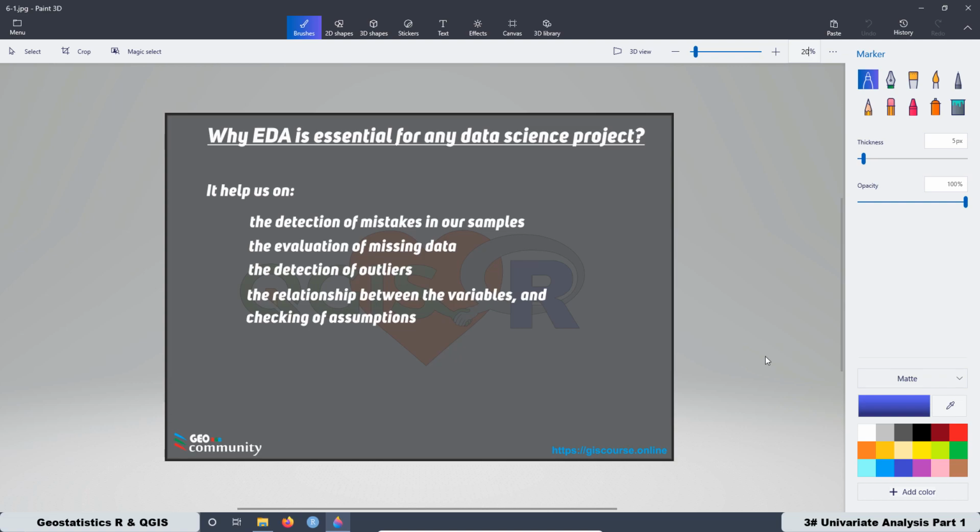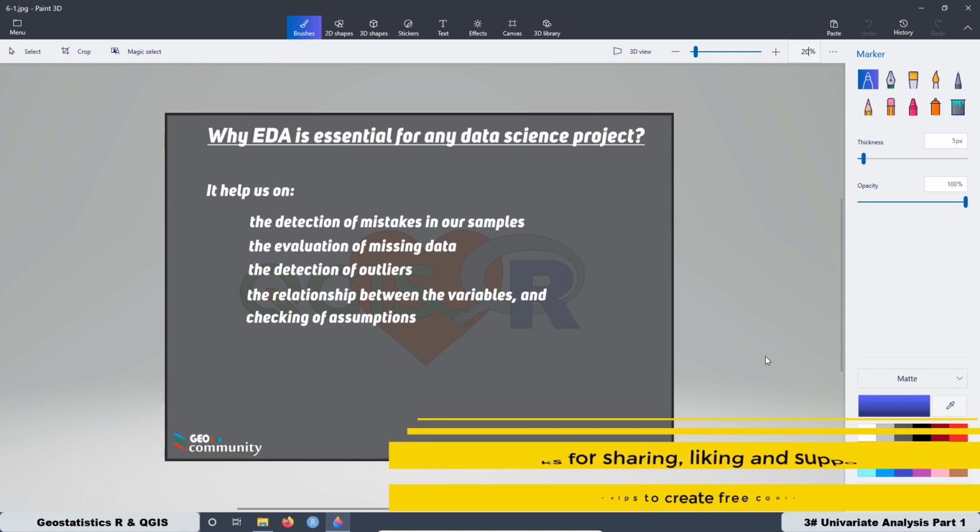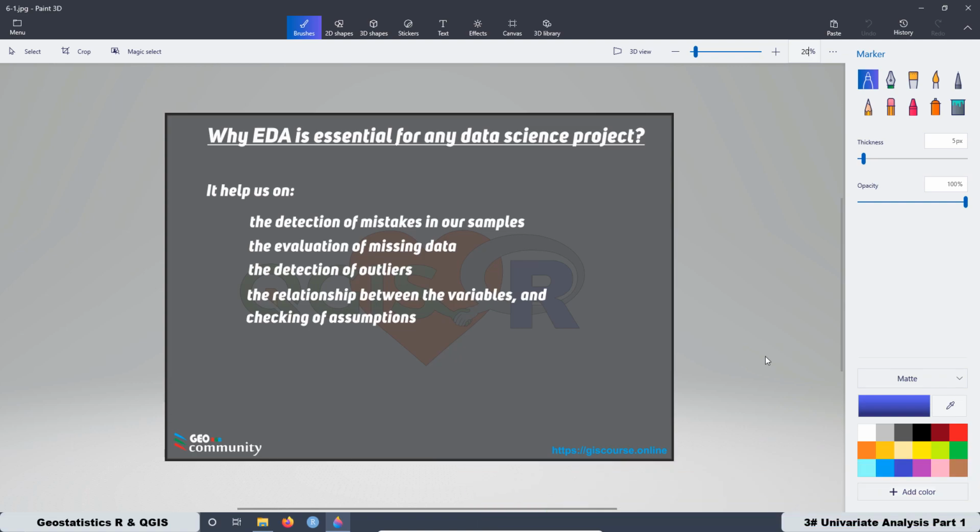If we are doing a model that is related with the groundwater flow direction, we want to know what is the relation between the direction of the groundwater and the X and Y coordinates to see if there is any trend. And we want to remove that trend from our data in order to use specific models that require that circumstance, right? I mean, remove the trend from the data.